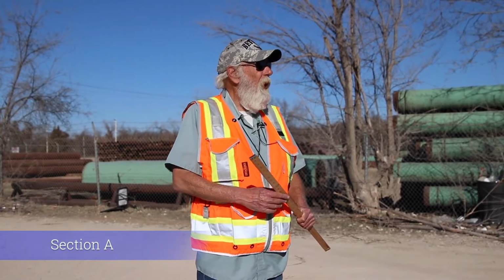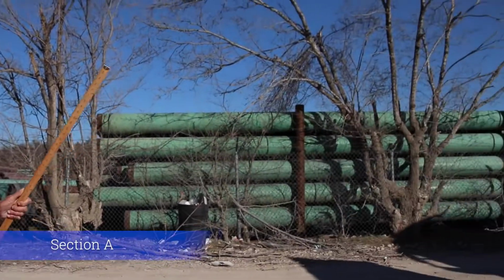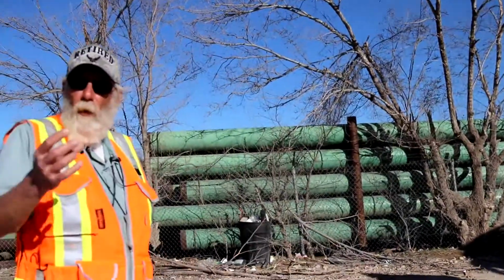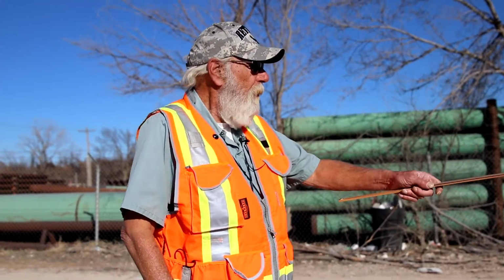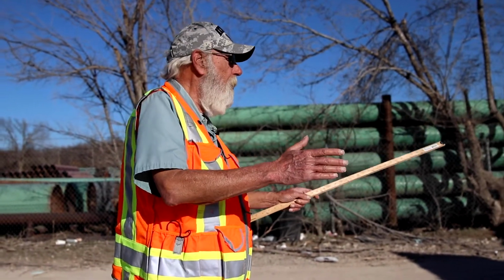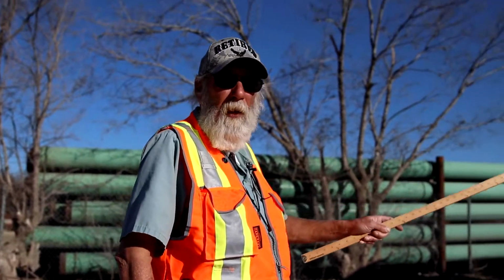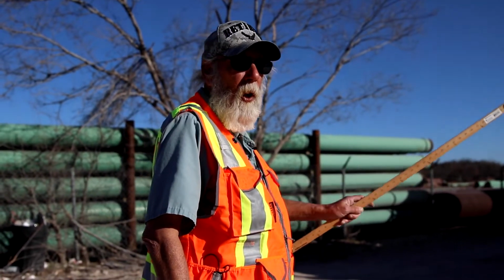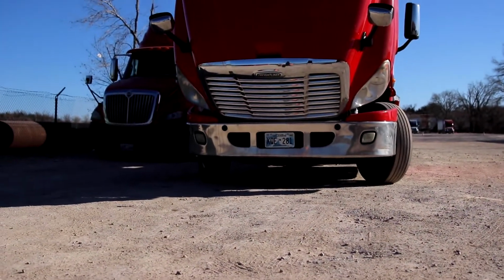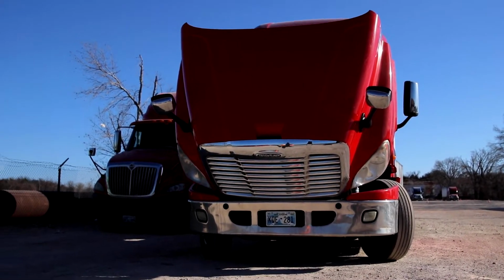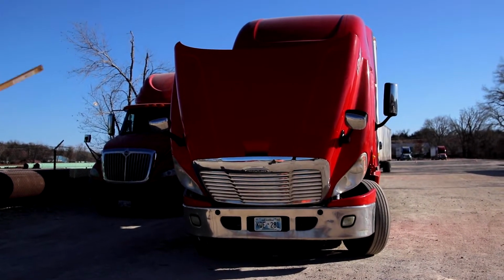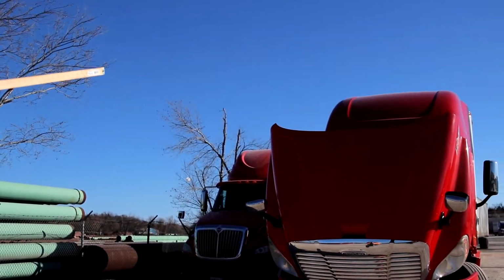We're now going to start with Section A. What you want to do is when you approach the truck, you want to look for the 3 L's: leans, leaks, loose hanging wires, and hoses. So as I'm approaching the vehicle, I want to see if the truck is leaning either left or right, which could be an indication of suspension damage, a flat tire, or even a load shift. Then I'm going to look underneath, and I'm going to make sure I don't see any leaks or puddles, and no loose hanging wires or hoses. That's your 3 L's.